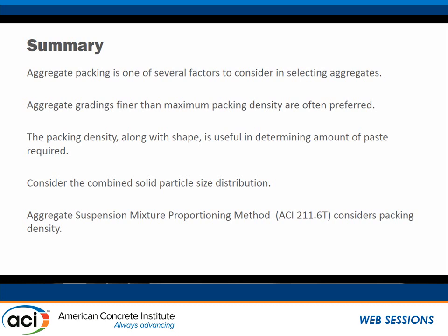And then the way to put it all together is to look at the aggregate suspension mixture proportioning method, which will soon be out in the next few months, ACI 211.6T, to look at packing density and then how all that fits in with the overall concrete mix design.